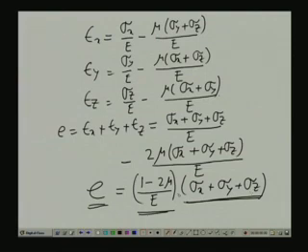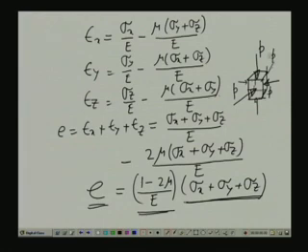Now, if we take that small body from which we have evaluated this quantity, and say that the stresses acting on this particular body, sigma x, sigma y and sigma z, are all of magnitude p and acting in the compressive direction on all sides, this we call a state of hydrostatic pressure. That means a body is subjected to pressure from all directions. Thereby sigma x, sigma y and sigma z are of equal value and of magnitude p, and this particular state of stress in a body we call a state of hydrostatic pressure.